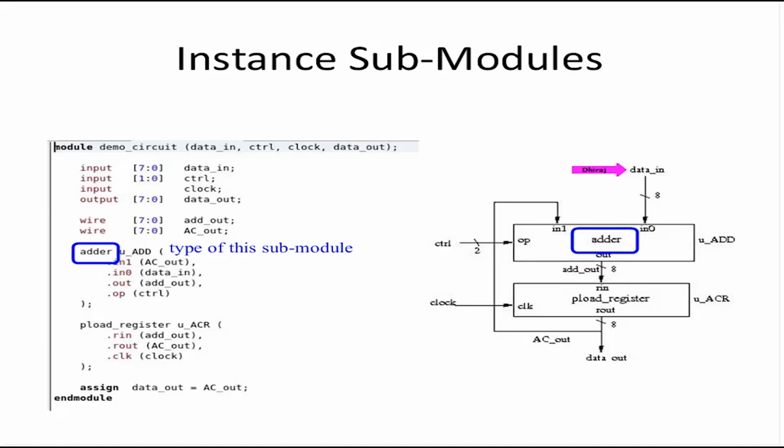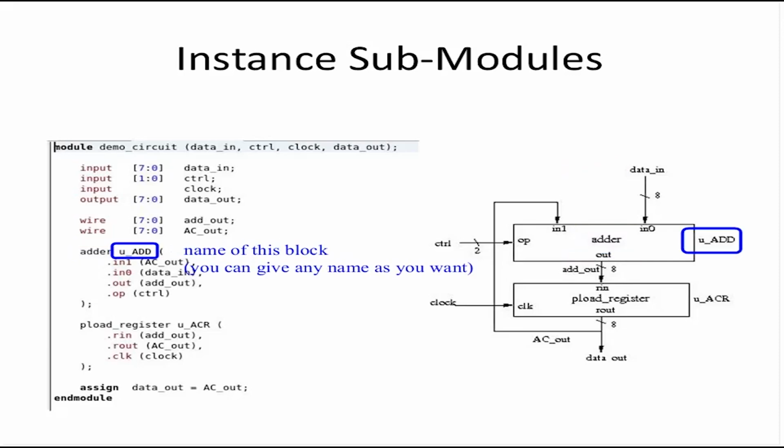Again, the register will be nothing but a bank of flip flops. The instance name could be anything, but it is useful to keep meaningful names so that you can know from the instance name. Usually we define the instance name to be the module name and add underscore inst to it, so it is clear from the name itself which module the instance belongs to.